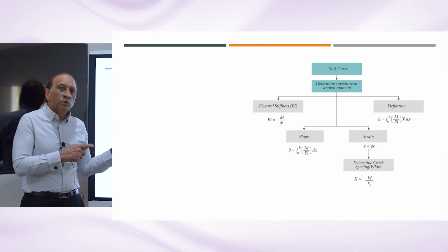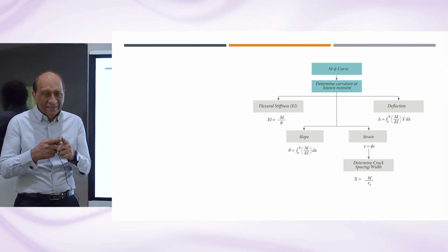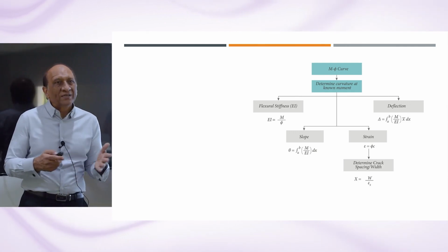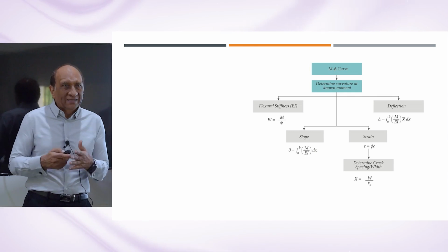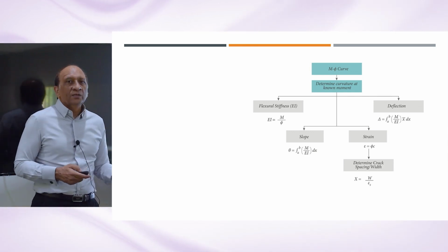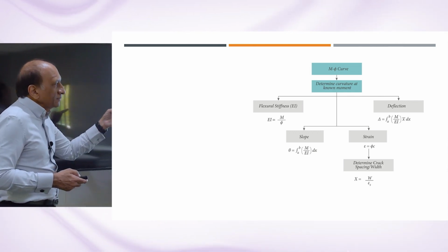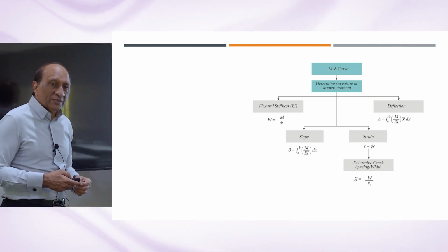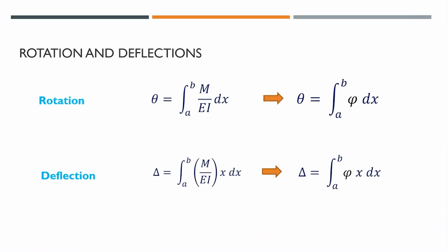So if we use the reliable stiffness from the moment curvature curve at every moment value, especially if the moment is large and it's already, in some portions, beyond the yielding, it's varying. We can use this after the cracking especially to compute the deflection much more reliably than any other approximation. So rotation, which is an integral of the curvature, we get that. And from there, deflection, which is an integral of the rotation, we get that.